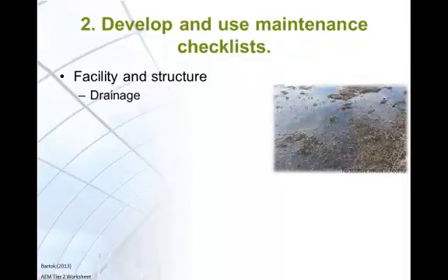Look for drainage problems. Pooling water is avoided by proper grading around the greenhouse. Landscape plantings should be kept away from drainage systems. Poor drainage may lead to frost heaving in the winter. Ensure that contaminants cannot enter drainage systems. Check sump pumps for proper operation.